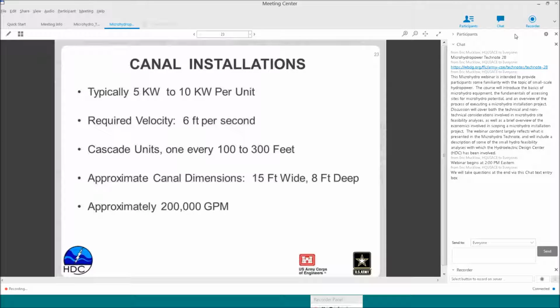As hydrokinetic turbines don't require a pressurized water passage, when they are placed in a river or canal, they can be placed in series with just enough spacing to allow the water to gain a steady flow profile, perhaps as little as a few hundred feet spacing between the units. As the hydrokinetic turbine is rather large and requires a certain velocity for the flow, we are presented with minimum parameters for the flow rate and profile of the waterway.